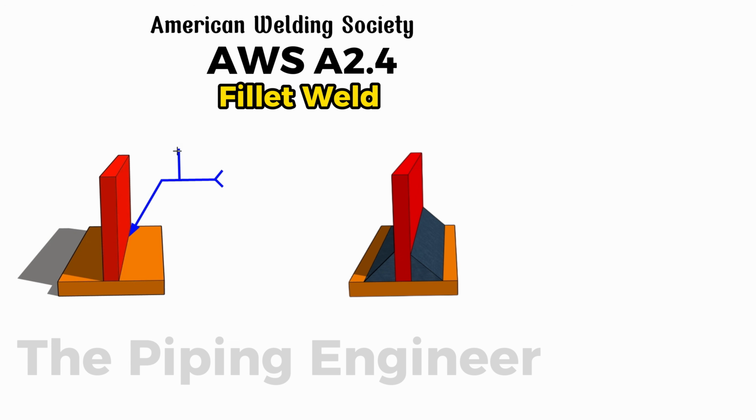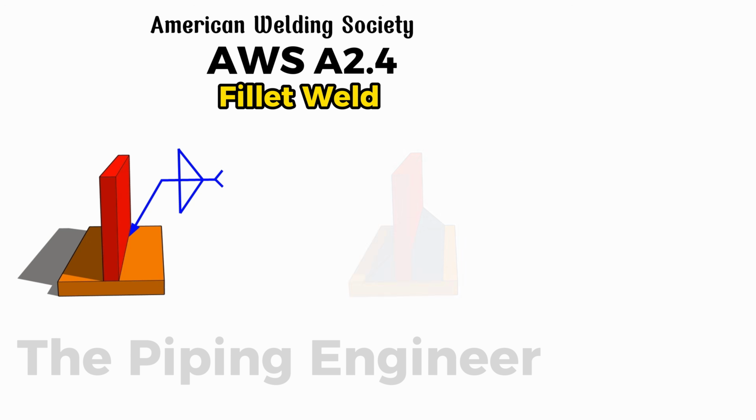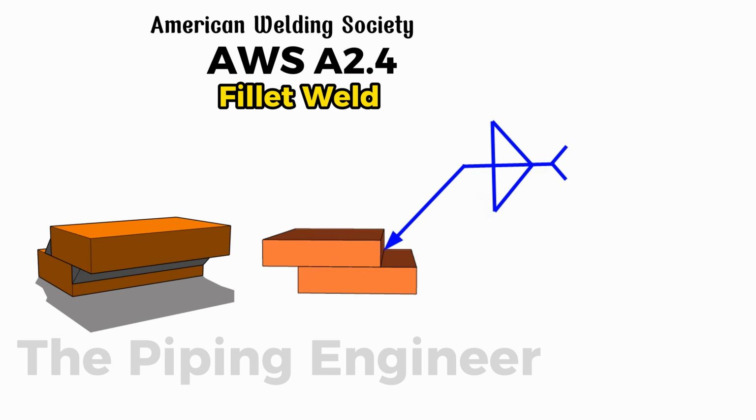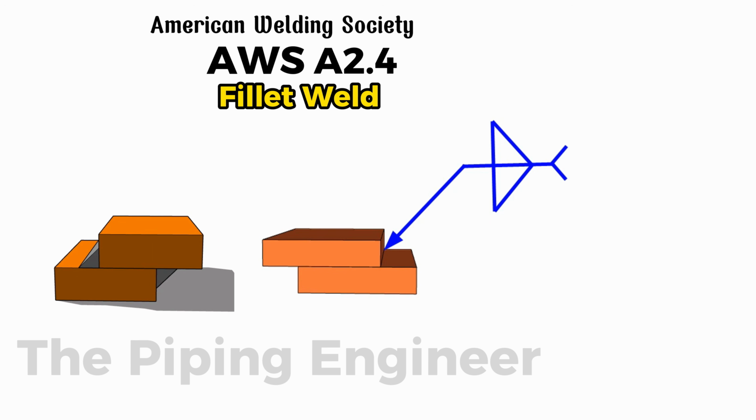If triangles appear on both the top and bottom sides of the reference line simultaneously, it indicates that the fillet weld must be applied on both sides of the joint. The completed weld forms an approximate right-angled triangle shape connecting the two intersecting plates or components. In lap joints, two overlapping plates or components are joined together by applying a fillet weld along the edge of one member against the surface of the other.